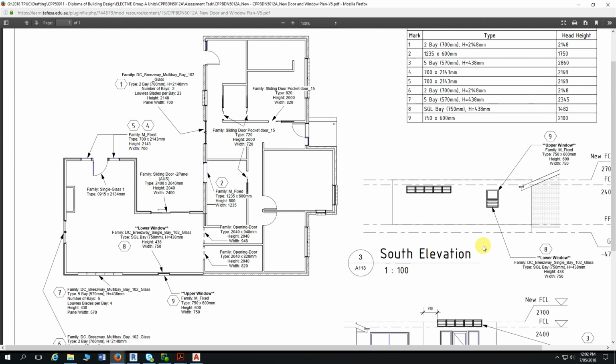Now don't forget that you don't have to place windows in a plan view. You can put them in through an elevation. If that's easier, that's what you do. So in this case, if you have to put one on top of the other, put one in first and align it in your floor plan, and then place the second one in your elevation and line it up there.